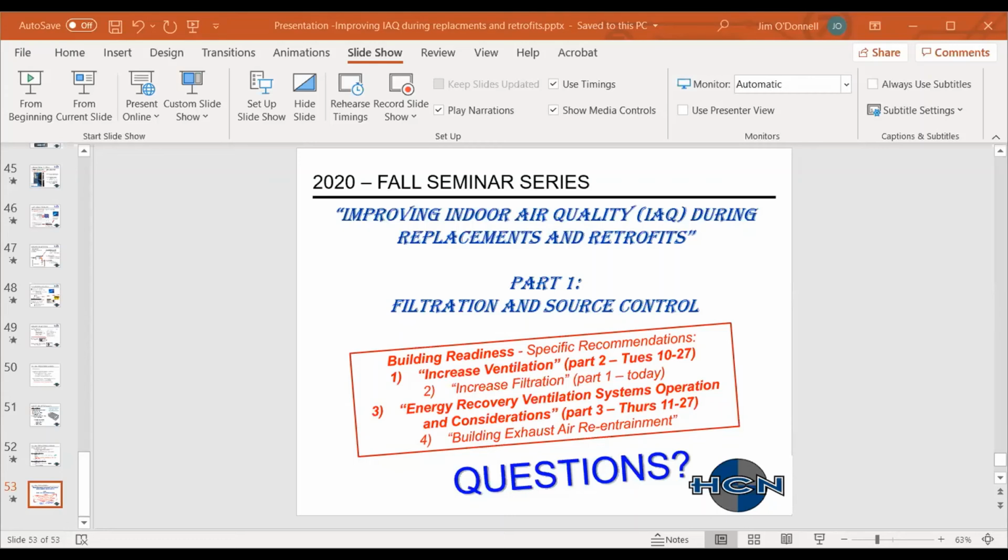Right. Okay. Second line of questions: someone wrote, I understand that most 1-inch, 2-inch, 4-inch pleated MERV 13 filters are electrostatically charged to achieve this efficiency and very quickly lose this performance to become a true MERV 8. Most true MERV 13 filters must be 6 or 12 inches deep. They call this a MERV 8 rating. Can you talk about this some?